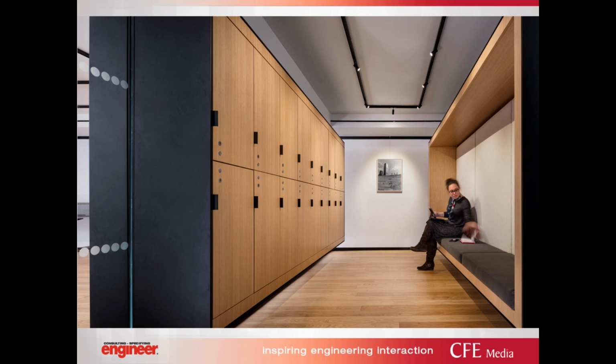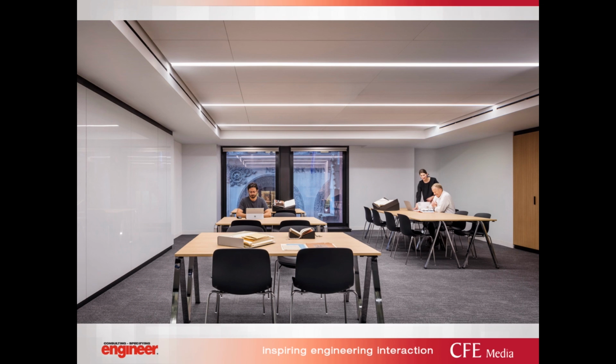Another thing we did in this space was use current limiting devices. In this case, we had a lot of track, as you could see in that larger gallery, but also in spaces like the locker rooms. So ensuring that we weren't going over capacity on those tracks was very important. The last thing we wanted to do was overlight one of the display walls, for example, and have the whole system go off. And then in other spaces like offices, we had high efficiency fixtures, and this is one of the collaborative classrooms. So we just used a simple lighting solution that provided a lot of ambient light.